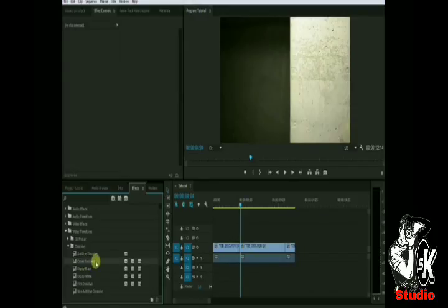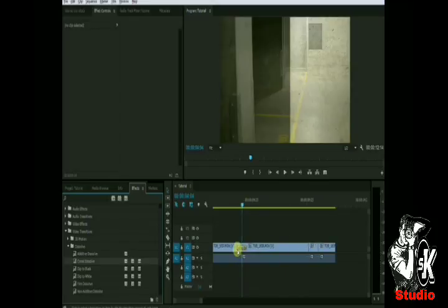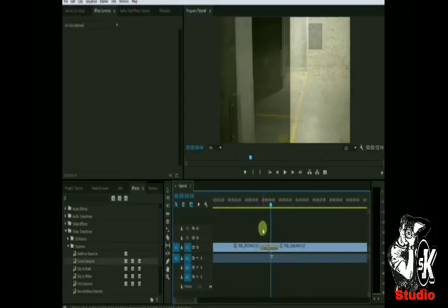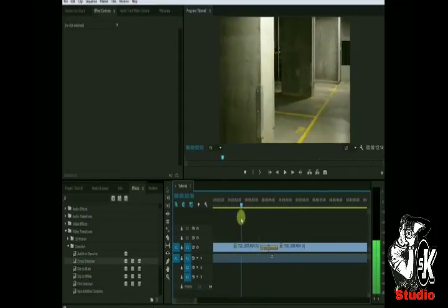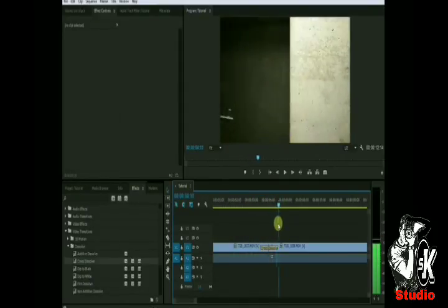The way to apply transitions to your clips is simply to select them and, like anything else in Premiere, just drag them onto your clips. You can apply them to the beginning of a clip, or if there's a transition between two different clips, just drag it onto the actual transition between the clips and let go. Bam! Let's zoom in a little bit. You will see that Premiere Pro added a Cross Dissolve to fade from one clip to the next. If you scrub through this transition, you will see that one layer fades very nicely into the next one.